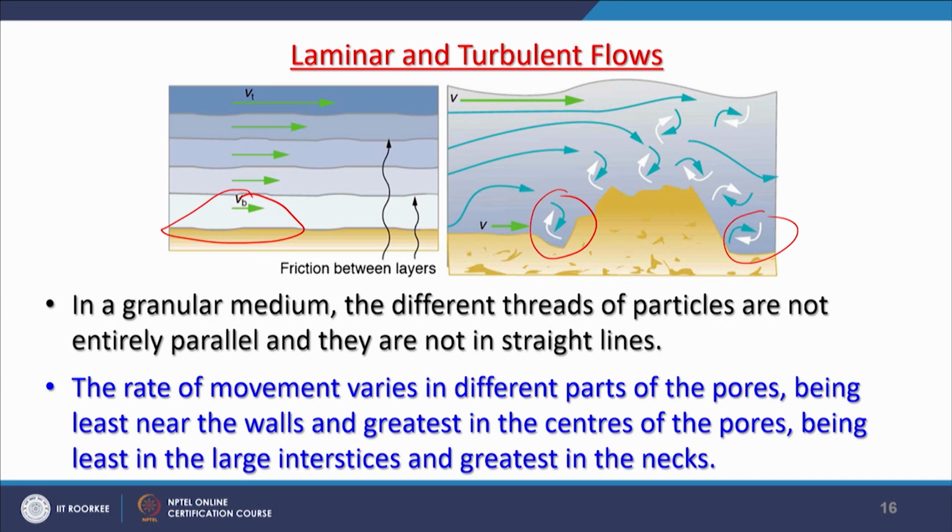So, let me link with groundwater. If you increase the discharge, if you pump out a lot of water from a well which was not designed for that kind of output, what would happen? Near where your pump pipe ends, there will be turbulence in the water, and the result would be damage to the well, and one day the well may become useless.